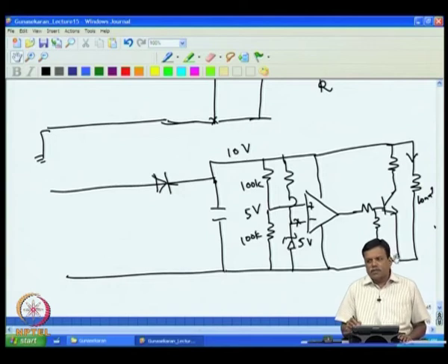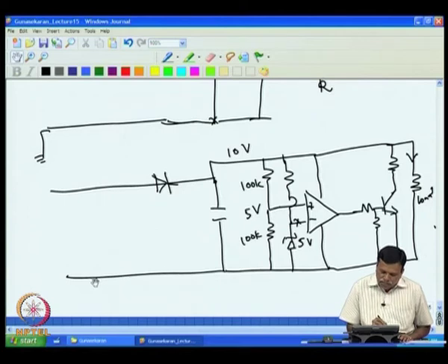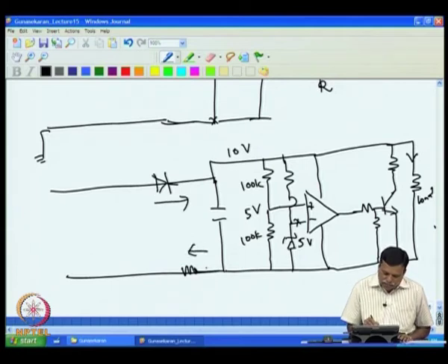Now, all that we have to do is convert this current, whatever is flowing through that, which anyway returns through this, and this current information will provide a signal. To obtain a signal, what we do is add a resistance here. So the entire current coming here actually flows through this.